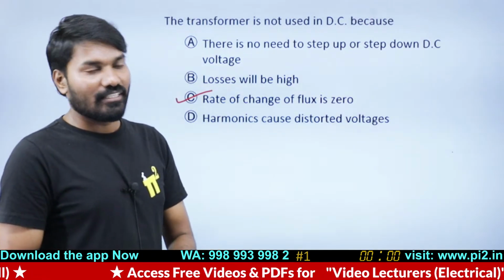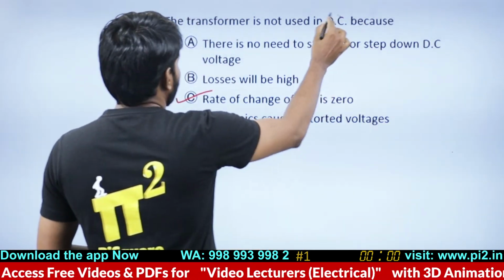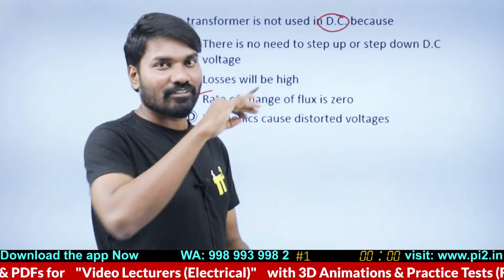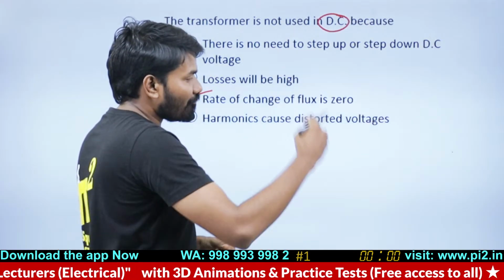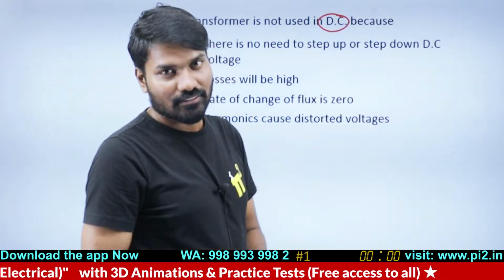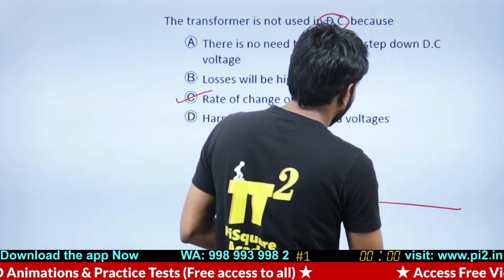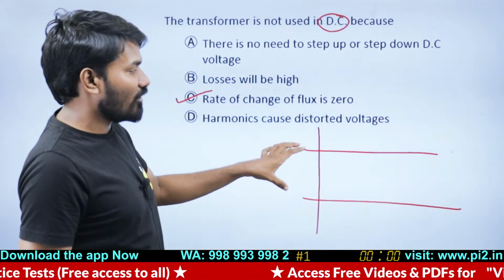Pulse transformer, yes. DC here means a constant DC. Even a pulse transformer will be damaged by a constant DC. But careful, guys, DC doesn't always mean a constant DC like this. This is a constant DC, a special category of DC.